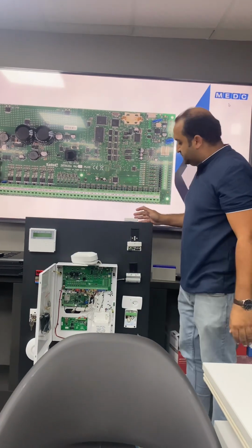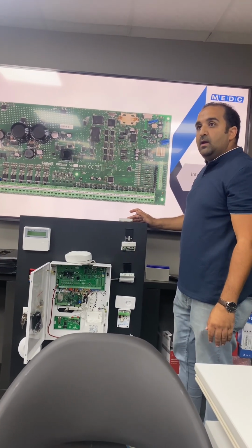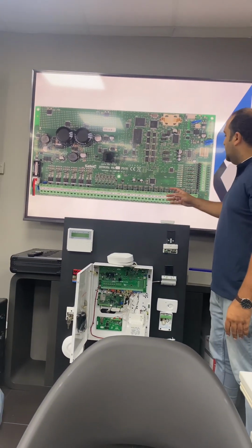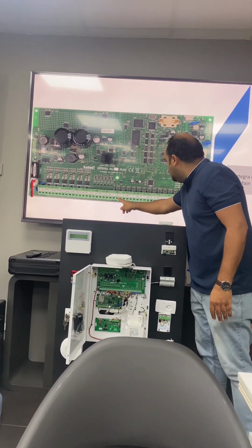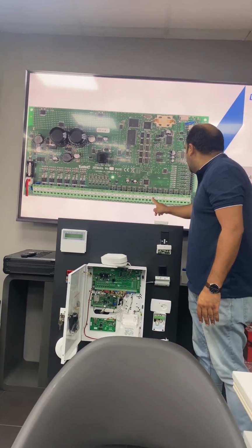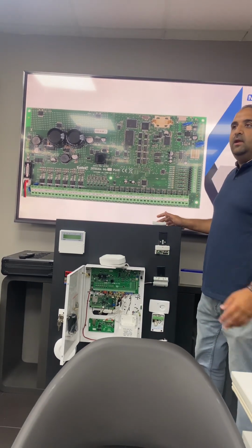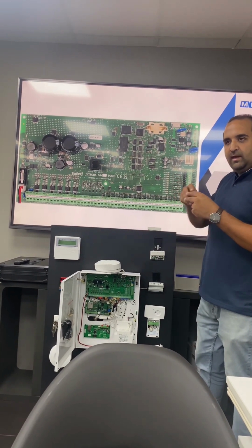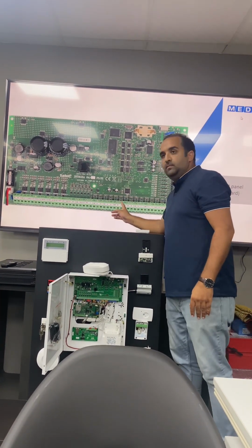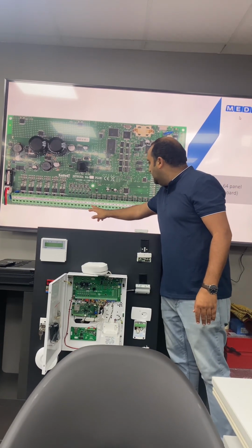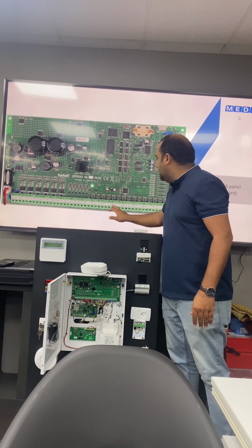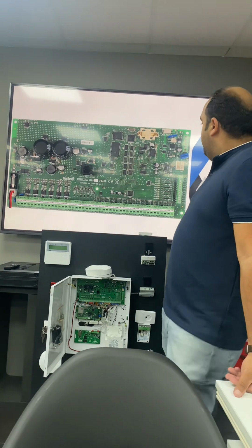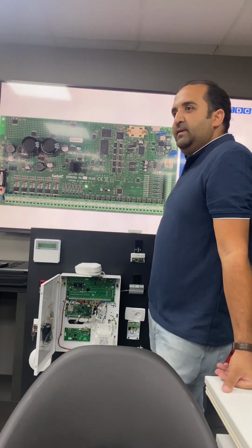Clear, right? So how many devices can we share on the common? Not only 2. You can share 3, 4, 5, no problem. But here, if you count, I think it's 8: 1, 2, 3, 4, 5, 6, 7, 8. That means you can connect each 2 devices on one common. So each 2 sensors take the common and connect to one of them: 1 and 2 here, 3 and 4 here, 5 and 6 here, like this. Any question? For the Integra 128, same.